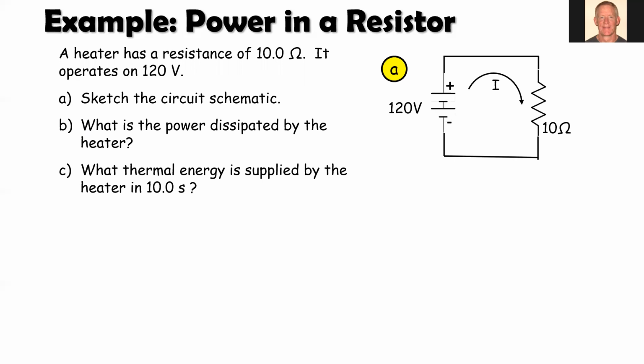All right, so here's our schematic. We draw our voltage source of 120 volts connected across a 10 ohm resistor that represents the resistance of the heater. Now, to measure the current, we've got to put an ammeter in the circuit itself. And to measure the voltage drop across the 10 ohm resistor, we're going to connect our voltmeter to each side of the resistance. Now, the voltmeter has basically infinite resistance. So when the current is traveling through the circuit, it's almost going to be like it doesn't even recognize the voltmeter as a possible path for the current to travel through. So it has very, very high resistance.